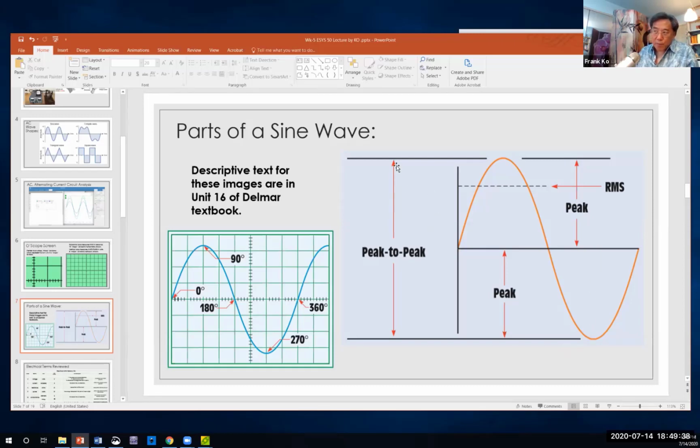And there's also something here marked as volts peak to peak, okay? From one peak all the way to the other peak. So if you know the positive half is 7 volts peak, and the negative half is symmetrically equal to that, so the positive half would be a positive 7 volt peak, the negative half goes to negative 7 volt peak. What would my peak to peak be?